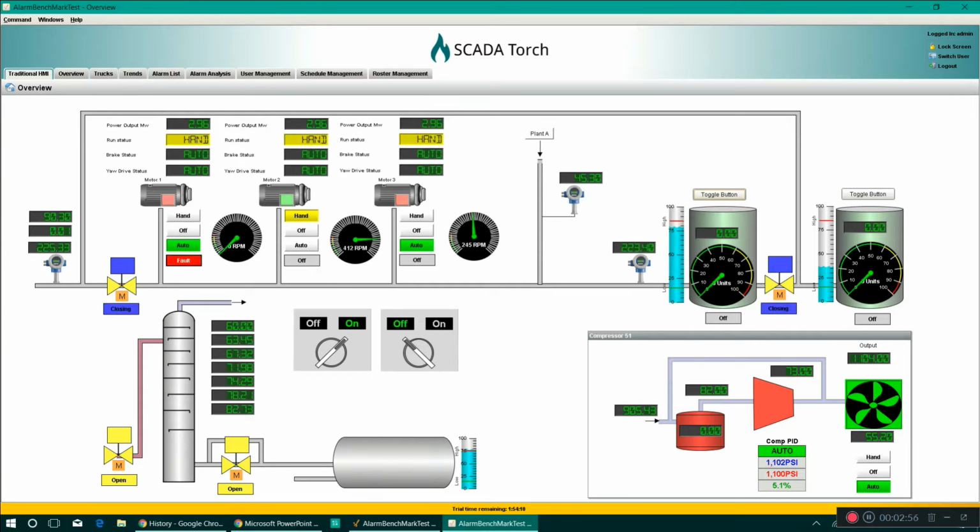Other things that we see on the screen: flashing indicators, lots of use of color to show different things. This type of valve might look silly to you, but I've worked on water treatment plants where it was called out in the spec up to 8 or 9 different colors for different states of a valve. So every color of the rainbow was in this valve to show different states, and it required lots of training for the operator to recognize and know what all those things were.